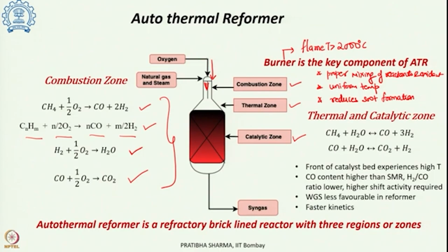These are the water gas shift reaction combined with steam methane reforming, and if there are higher hydrocarbons, then pyrolysis reactions of the higher hydrocarbons can also occur. So, in the thermal zone, various gas phase homogeneous reactions occur, including steam methane reforming and water gas shift, as well as various hydrocarbon reactions.